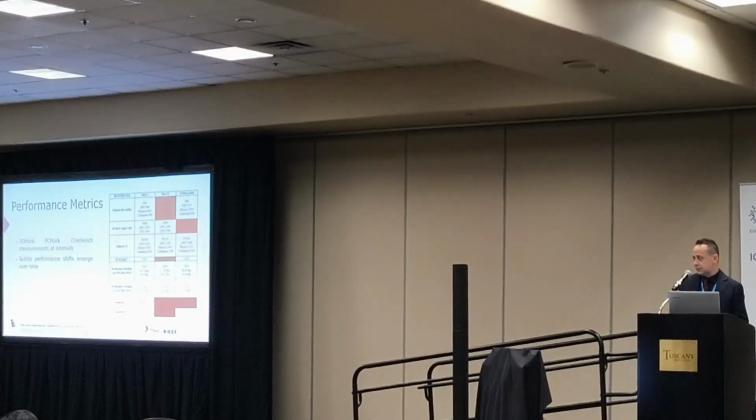And the experiment finished at the failing point, which means that the CPU started to give signs of failure, like the system becoming unstable, sometimes not being able to load the operating system, or just freezing. So these are indications that something is failing in the system.